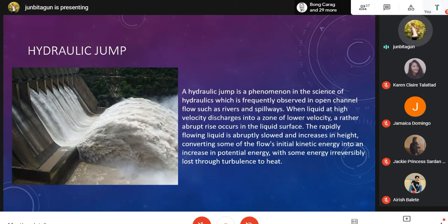So, when does a hydraulic jump happen again? It's not just that a barrier was placed so a hydraulic jump occurred, but that's one way. There's a sort of ramp so the flow goes upward. There are variations in the flow, not just flowing along an open channel, and then it suddenly jumps at the barrier that was placed. Because of that, the fast-moving water is suddenly slowed down. That's the idea: you suddenly stopped it, so it rose to balance out the energy.